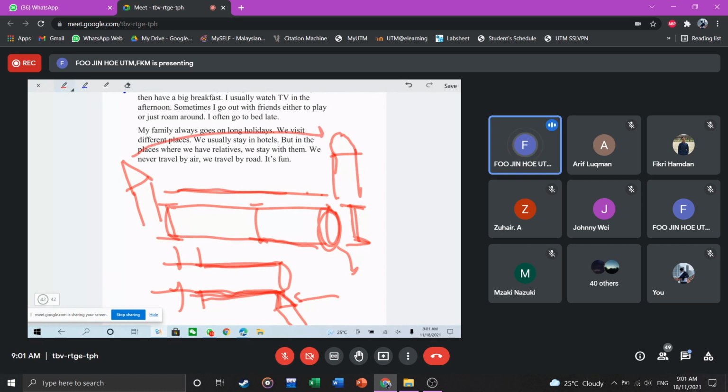Then later on, this cutting tool might become blunt. So you need to resharpen it, recondition it, all the time. So this thing is very difficult and very subjective. First of all, we do not know when it will become blunt. We do not know when the wear and tear will happen. And also it is based on the skill of each and every machinist working on it.